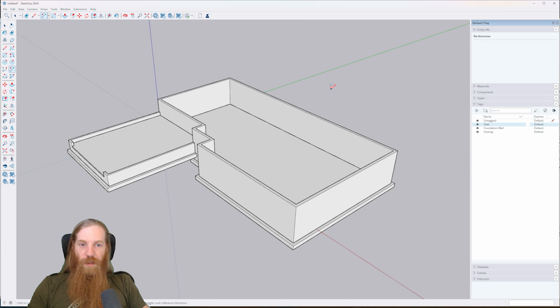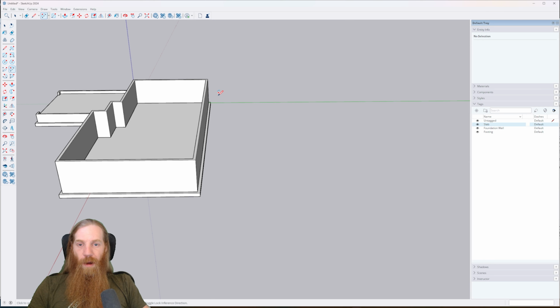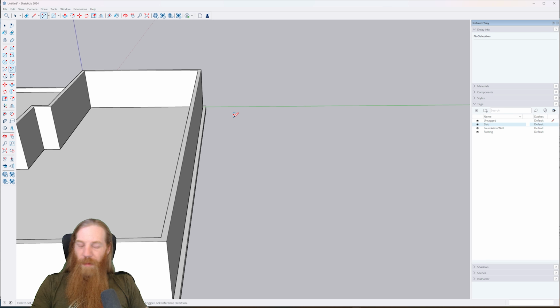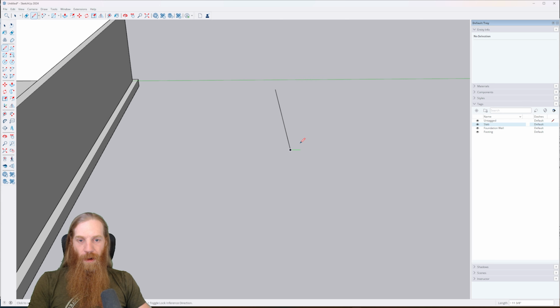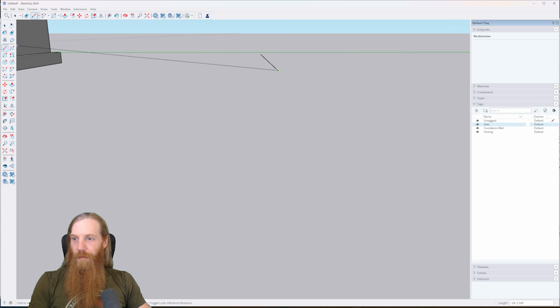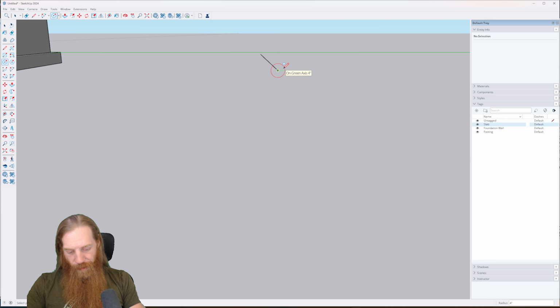It draws a circle from the center point. So what you would do is find the center point of, oh man, I'm going to have to do a whole other video on how to do it. It's a little more advanced. But I could show you real quick on one that doesn't have a bend on it. So let's do a line on the red axis. We come down here, we look at the end of it, right? I just do the circle off of that. A number 4 rebar is going to be 1/2 inch, right? So let's do 0.5 inch, type that in, hit enter.